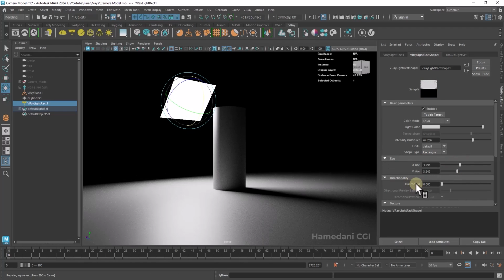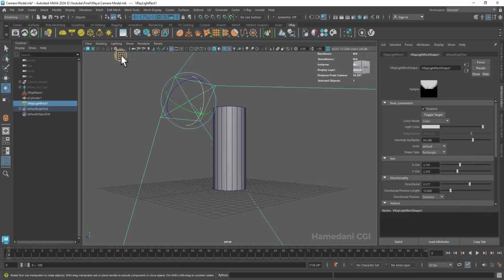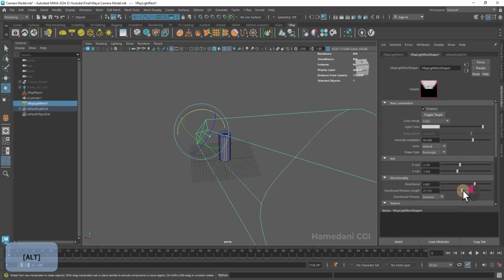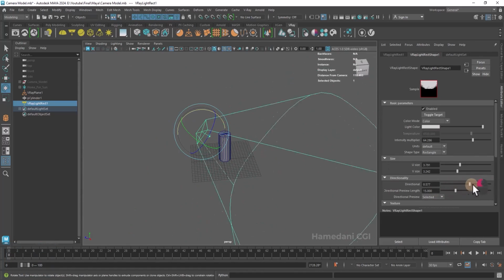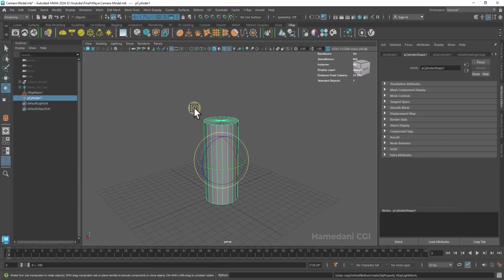Directional. It concentrates light. And you can control the cone, the length of the cone. Light mesh. This makes an object illuminate like a light, but if the number of these is higher, it causes the render time to increase.